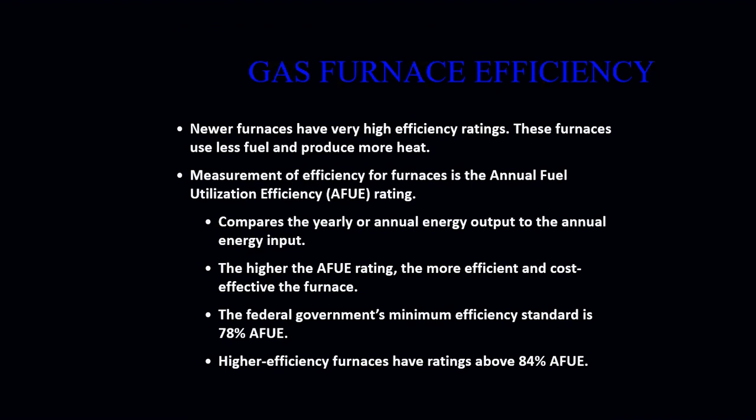The higher the AFUE rating, the more efficient and cost-effective that furnace can be. By federal standards, we have a minimum efficiency standard of 78% AFUE, which means every furnace being manufactured cannot be less than 78% efficient.